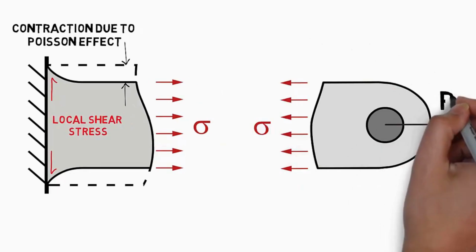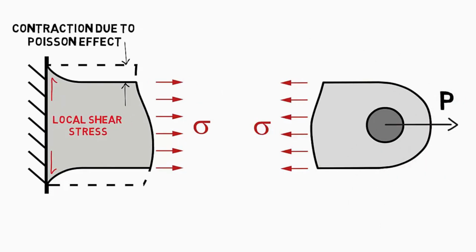Similarly, for the pin connection end of the rod, load introduction occurs through the pin, thus stresses in the rod are initially concentrated around that pin and have to flow around the pin hole before they can redistribute into a more uniform stress state further along the rod.